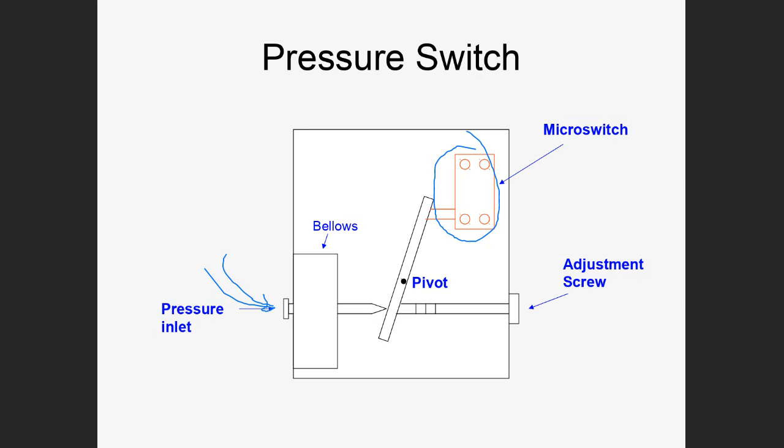And we can sense the voltage change, and you can relate that to a certain amount of pressure. These are the same type of crystals that are used for a crystal watch. If you have a watch that keeps time, it's based on the vibration of a crystal. These crystals, if you squeeze them, produce a voltage.